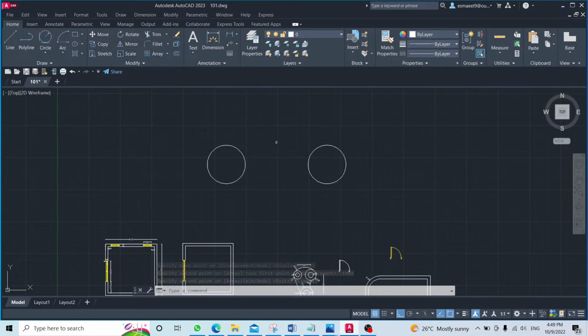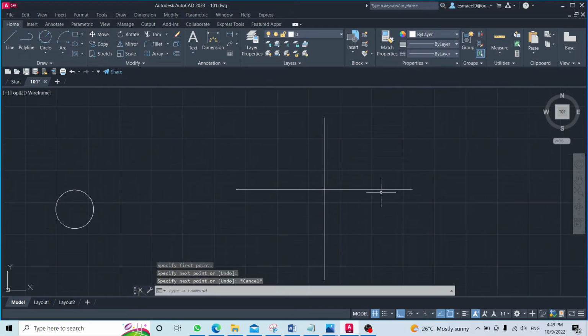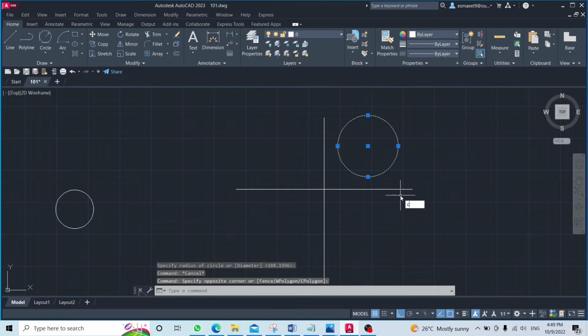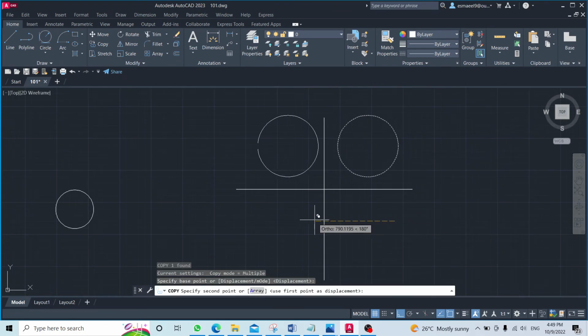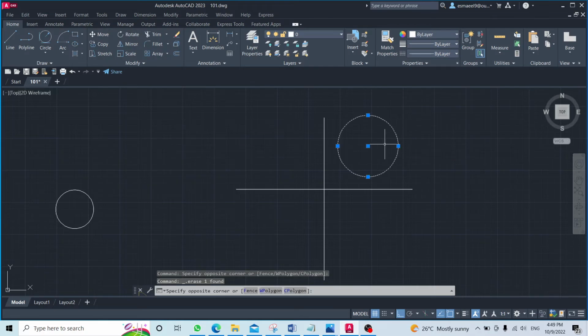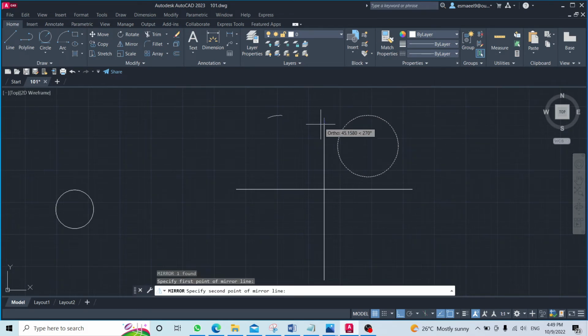We talked about mirror. If we have a shape like this, I do have a shape in here and I want to copy it into this place. I'm able to select it and say CO and go like this, right? I'm able to make it. But what we said is you are able to even select this shape, click MI for mirror, and click space, click your first line.